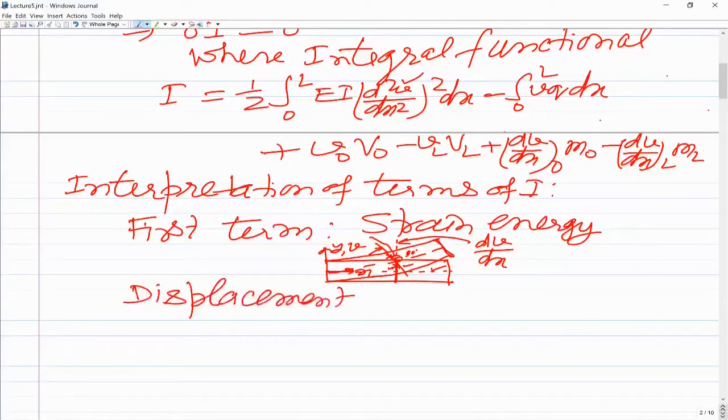So if I look at the displacements, one is the axial displacement. So u, which is a function of x and y, will be equal to, because this distance is at a distance y, and it's along the negative x direction, minus y into the angle.